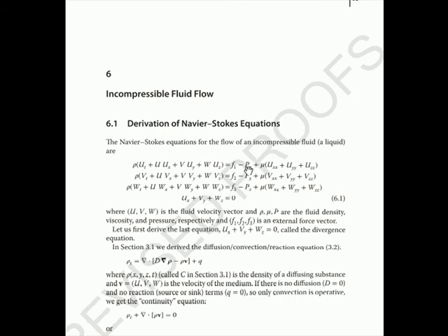Basically, one of the main problems with these equations is that pressure appears in first derivatives of pressure. There's no boundary conditions on pressure. The pressure is really the problem, and it gets rid of this equation. So this is called the penalty method, and it's basically just backing off a little and saying, well, the fluid's not quite incompressible, but it's almost incompressible.